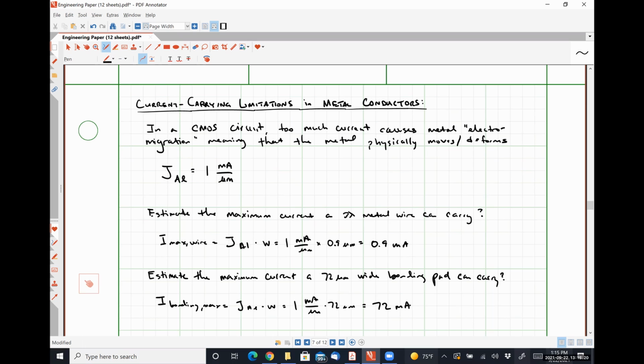Why do you think there'll be less? That's fair. Okay. Another way that you could think about it would be you have less squares, right? If you make your wires wider, then they're occupying less squares. And so if there's less squares of sheet resistance, there's less resistance, right? So, yeah. All right. So that's a fairly straightforward topic.